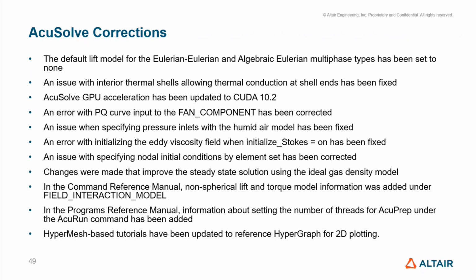And initialize Stokes now initializes the eddy viscosity field correctly. An issue with specifying nodal initial conditions by element set that was reported has been fixed, and ideal gas steady state runs have been improved as well.